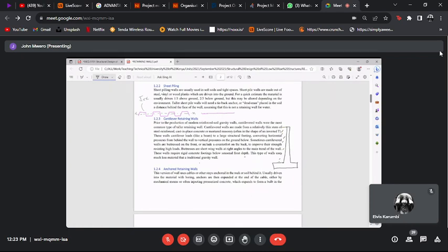They're usually made of reinforced concrete, and it's basically a cantilever that way. So we analyze and design it like an inverted cantilever. It's being loaded here, and it is fixed at the bottom. We'll run a design on that, and then it will become clearer.